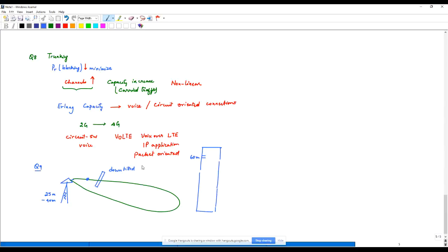What is the answer to this? Typically, the cell phone tower must be one of the highest points in an environment. So there must be another cell tower which operators will set up. Probably they will leave this tower alone, but they will find another building of the same height and use that to cover the upper floors. So the answer to your question, very good one. The advantage is that if this down tilt is slightly modified, you can still get a good signal. And the reason you can get a good signal is there is no obstruction. You will get almost line of sight.